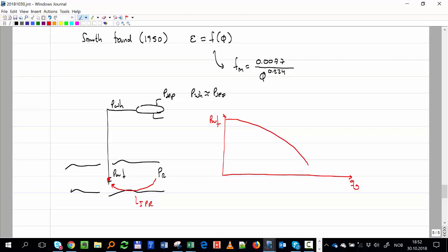We have to look for the other boundary, right, where we have constant pressure. Where is that? Separator. And we have to go counter current all the way down here, right, to compute that pressure. So for that, I'm going to use that expression, PF equal to PWH plus QG over CT. And I'm going to use it exactly like that.